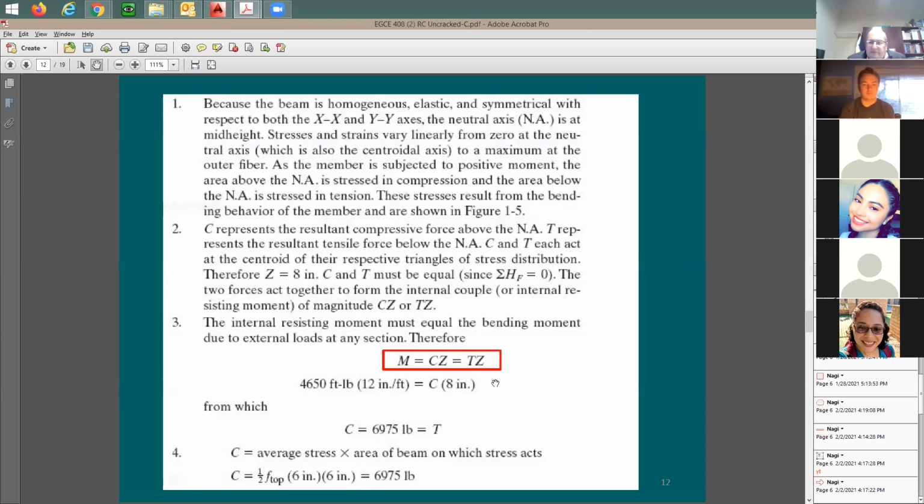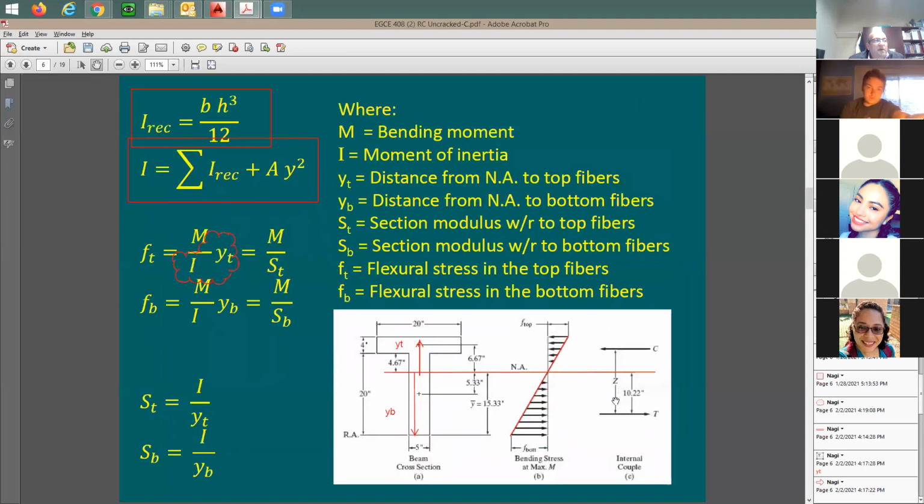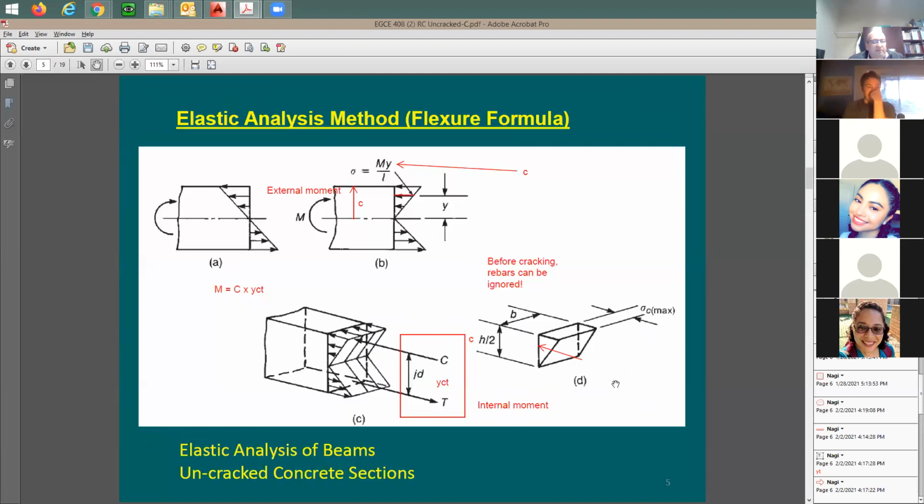So what do you do after this? Let me take you back here one picture, to slide number 12. We said that you're going to be doing integration. And when you do the integration, this force is going to be equal to the integration of this stress block. Now, this force I have because I did the analysis. And this force is going to be equal to the stress times this depth, h over 2, divided by 2 for this area of this triangle face, multiplied by the width b. I'm going to do exactly the same thing.